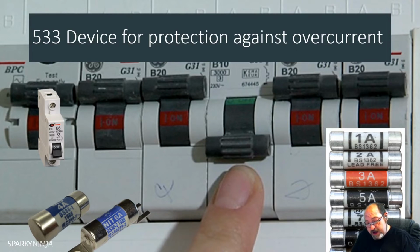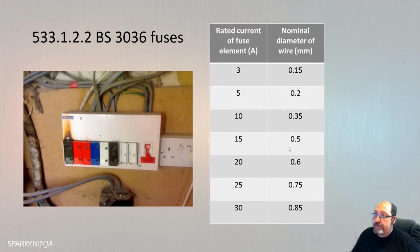533.1.2.3. A fuse shall preferably be of the cartridge type. Where a semi-enclosed fuse is selected, though, it shall be fitted with an element in accordance with the manufacturer's instructions, if any. In the absence of such instructions, we have to have further guidance, and that's given in this table here. And I've used this illustration just to show you what can happen if we don't follow the guidance. So this is a good example of a 5 amp that kept blowing, so they probably put a 15 amp in or something.